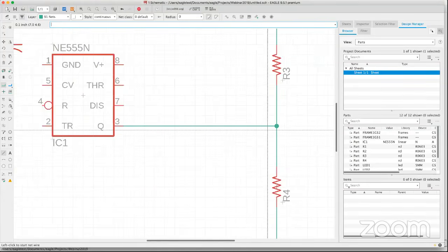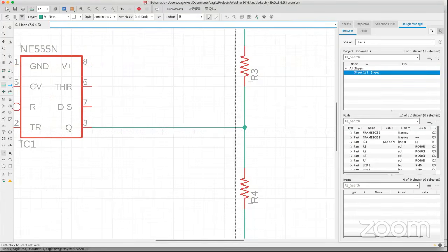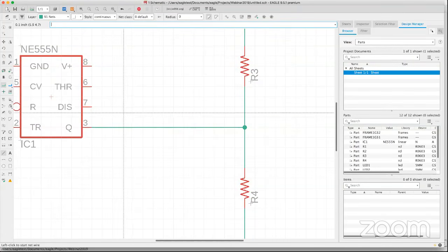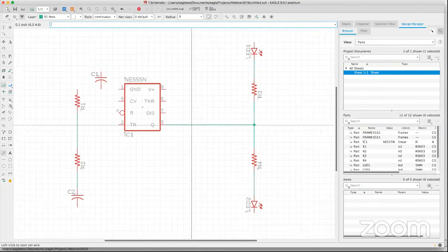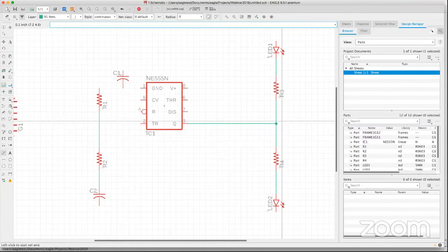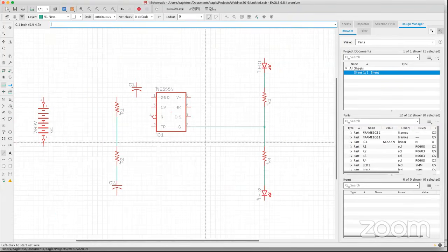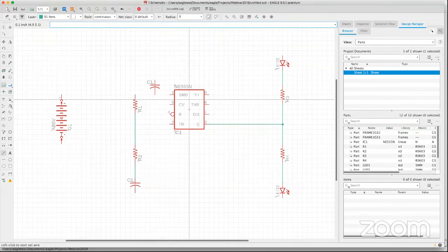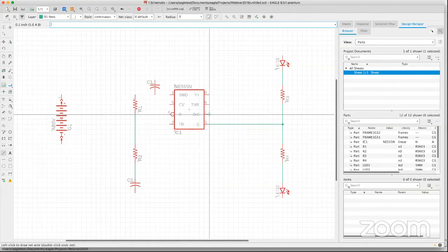When you do an intersection between two nets, junction points automatically show up. So every time I draw a net from one net and stop at a different net, you always get that junction point. This lets you know that the signal name on both lines that are drawn actually have the same name. That's why that junction point is kind of important. I'll go ahead and continue drawing the rest of my connections.